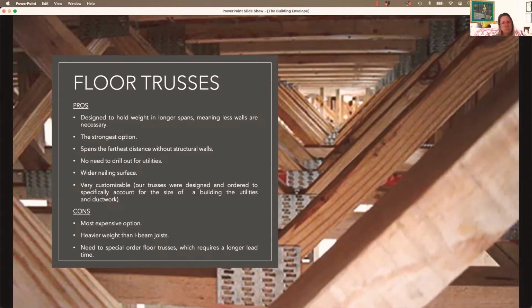It might be a larger house, or maybe it's a house that doesn't go up as much but is wider, more of a ranch style that needs to distribute the weight more evenly. Just depends. And it also could always come back down to cost, because you can get some of these attributes by using the bridging in the regular stud or joist system. So it could be something that comes back to cost for whether or not they decide to use trusses over joists.